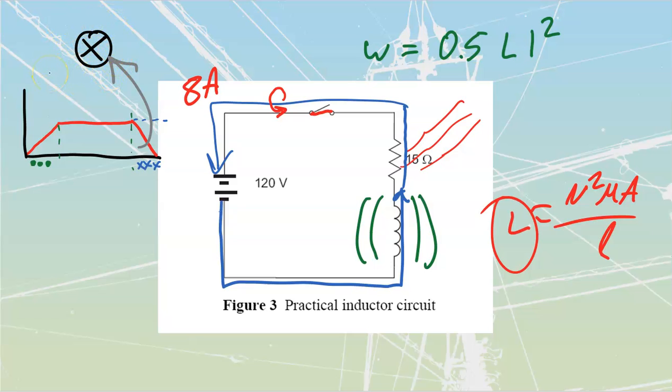Let's talk about what happens when we open up a switch, because it's a really dangerous thing if done incorrectly, but it's a really useful thing if done properly and correctly. When we open a switch, we know that it's not actually an infinite amount of resistance. We treat it like it's an infinite amount of resistance, but in reality, it's just an air gap.